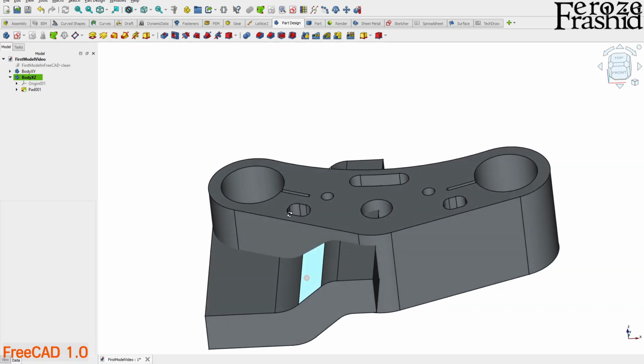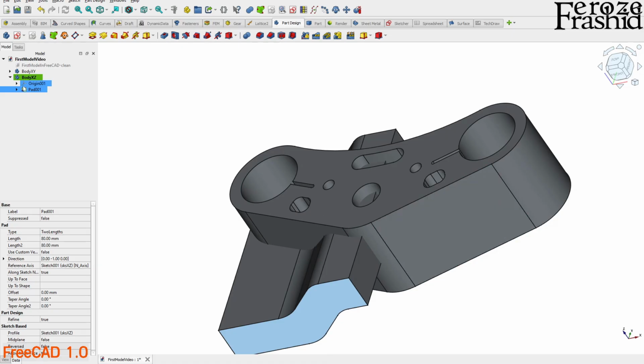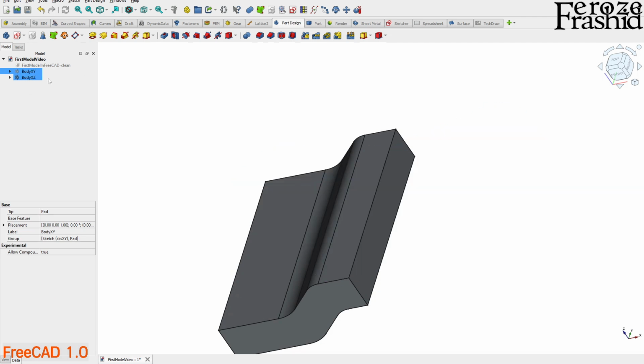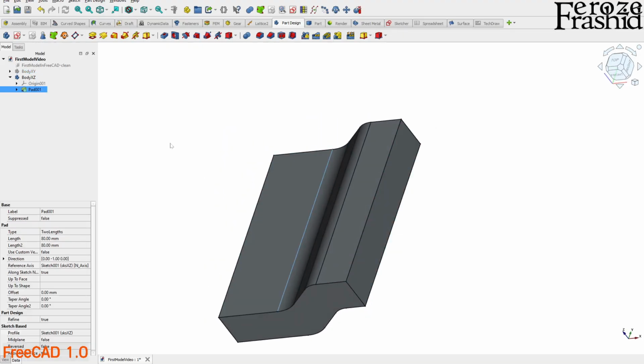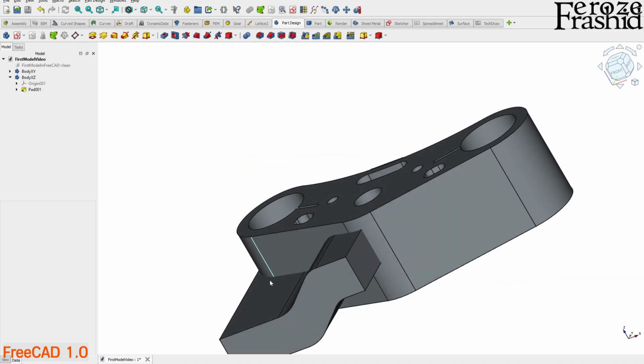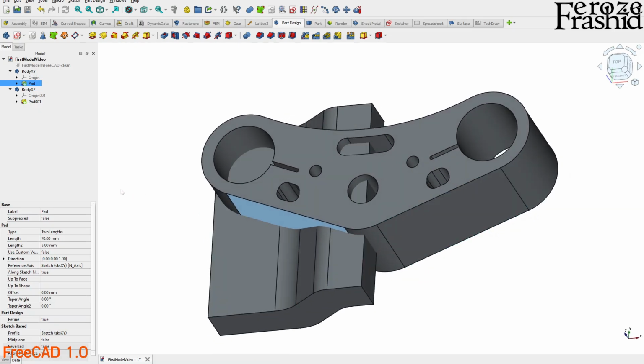All right, so we got two of our bodies, but this is half, right? And I'm gonna go ahead and mirror it over so we can have like a full body. So then when I mirror it over, I will explain it just a little bit more, but notice how these two bodies are differently selectable. So this is like if I hit space on the body, you can see that it's gone. So this is a totally separate body. So we have two different separate bodies, can be selected differently, and can be done whatever we want differently, separately.